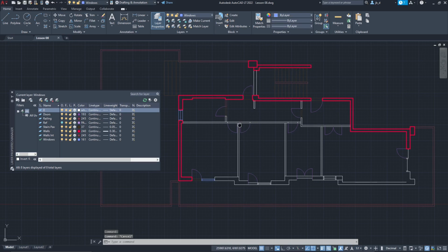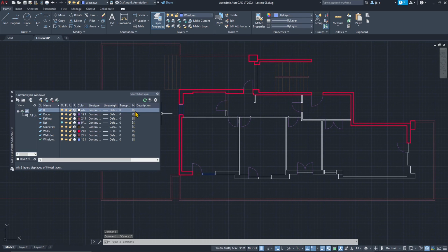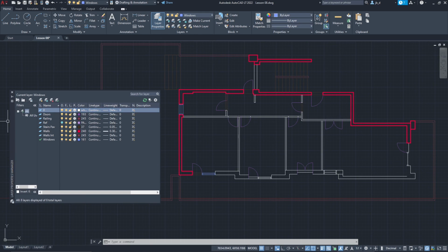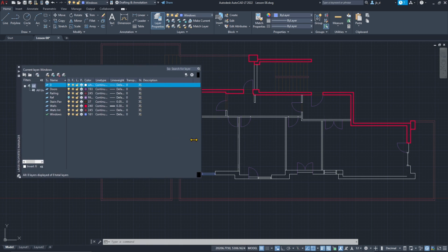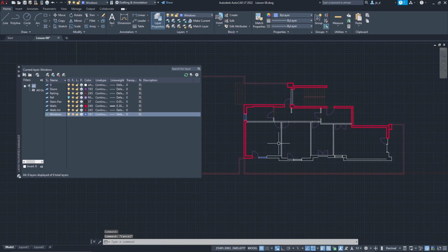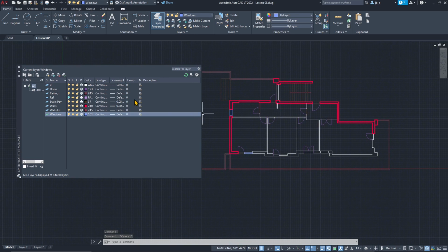In this video, we're going to see how we can work with layers in AutoCAD. So layers are used for managing and organizing your project. So they are actually a project management and organization tool. And also, as anticipated in other videos, layers can be helpful to distinguish various parts of your project, like external walls or interior walls or stairs or doors and windows and so on.